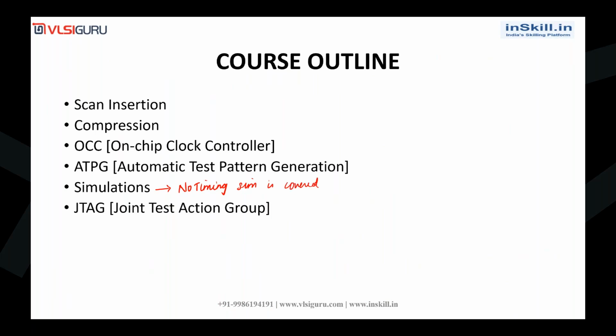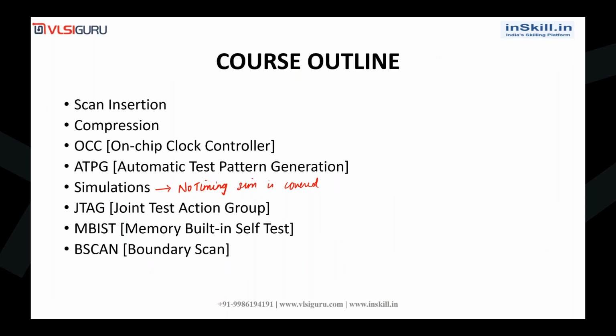Okay, and next is JTAG. JTAG stands for Joint Test Action Group. Then memory built-in self-test, and then boundary scan, B-scan. This JTAG is an IEEE 1149.1 standard. We will also be covering IJTAG, which is nothing but the IEEE 1687 standard.